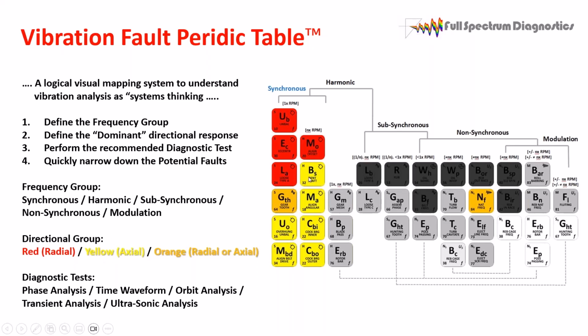So that's unusual. Usually all our response comes from looseness and unbalance and misalignment and things like that. The yellow group produces 1 times RPM as well, that's in alarm, but it's a different phase relationship, a different motion, if you will.